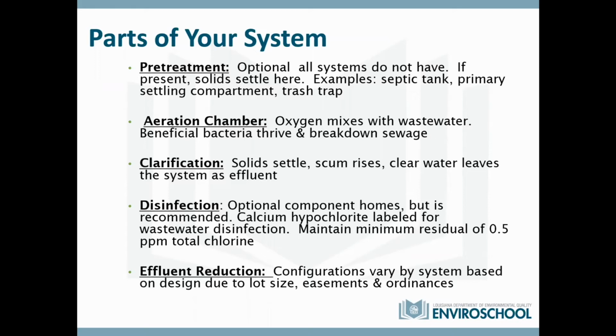And then if you have disinfection, and I say if because these are optional for homes, the way I understand it in the sanitary code, disinfection is encouraged for houses, but it's not a requirement. But if you have a DEQ permit for a business that has your own sewage treatment system, and I think also the same with the Department of Health, I'm pretty sure it is a requirement. And I know for DEQ, because I work for DEQ, you will have effluent limitations that do require some sort of disinfection, because you have to get some of your coliform levels down. So it is a requirement to meet your effluent limitations at the very least for DEQ.